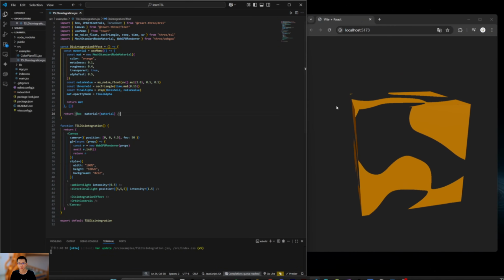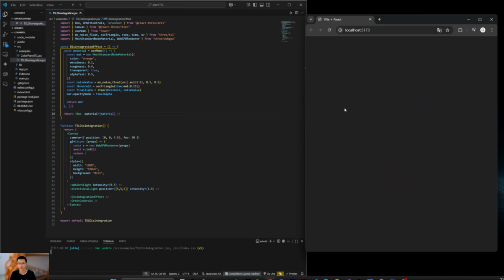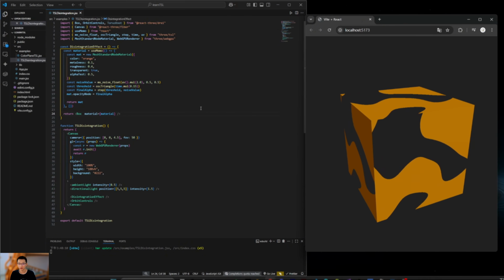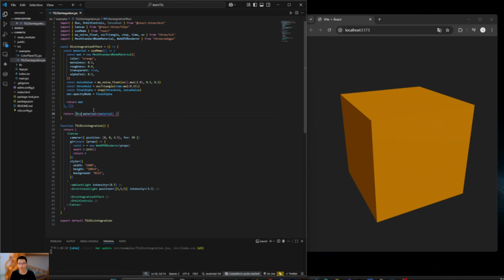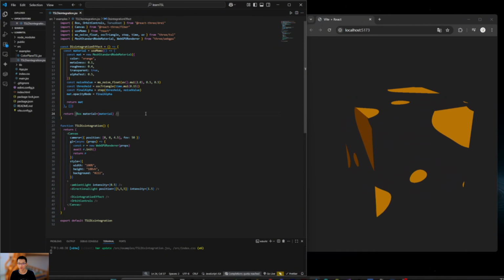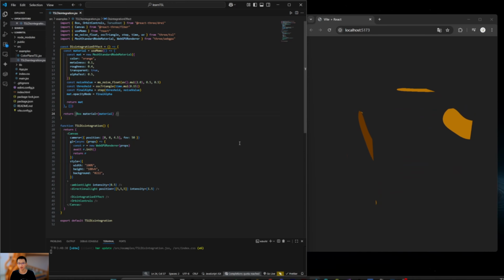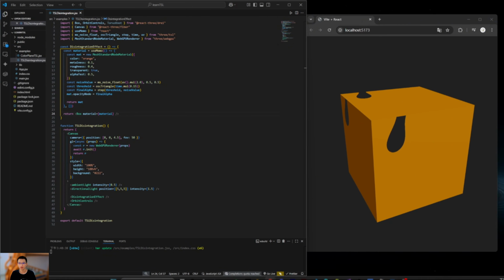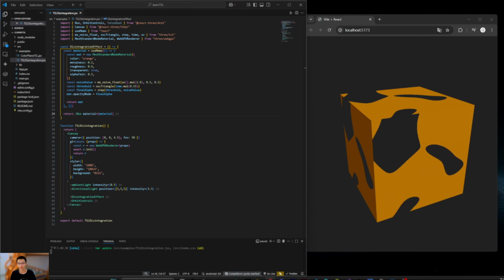Let's do a quick recap. The whole process is like building with Lego. We use the mx_noise_float node to create the base dissolve pattern. Then we used oscTriangle with time to generate a dynamically changing threshold. Finally, we used a step node to compare the pattern with the threshold, deciding which parts stay visible and which parts disappear. That's the beauty of shader programming. Just a few simple nodes can combine into endless visual possibilities.